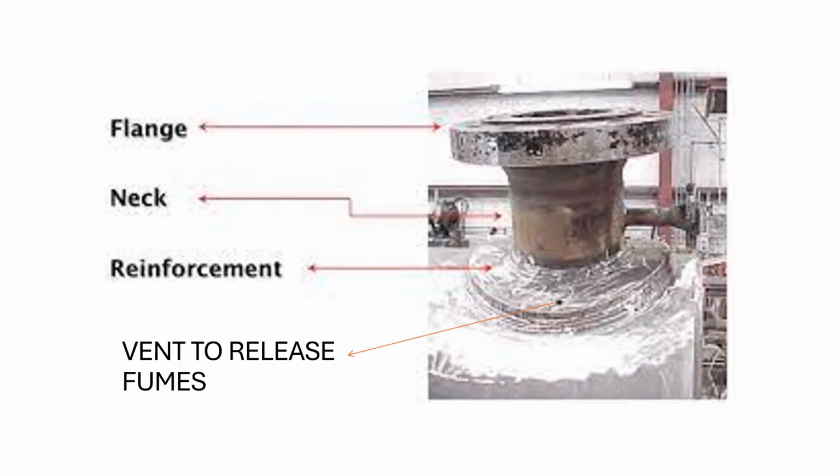Okay, so moving next, you see this is a flange on a vessel. This is a vessel shell, and this is reinforcement. This is the neck of the nozzle, and this is the flange. Here they have used a WNRF flange, that is weld neck raised face. Here you can see a raised face over here.